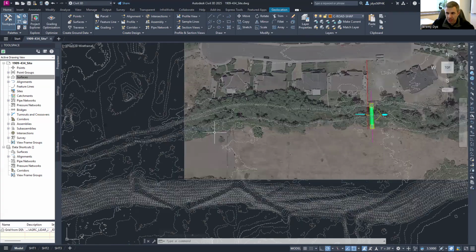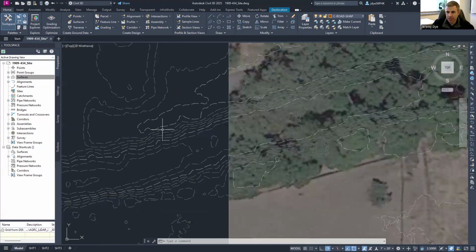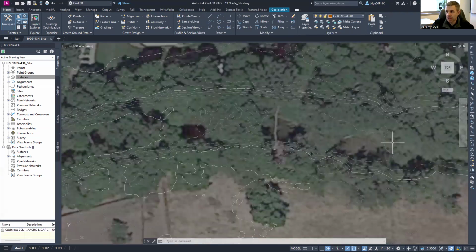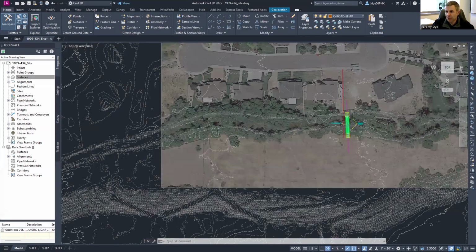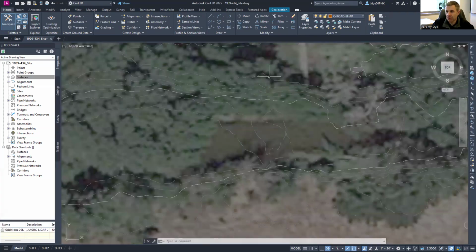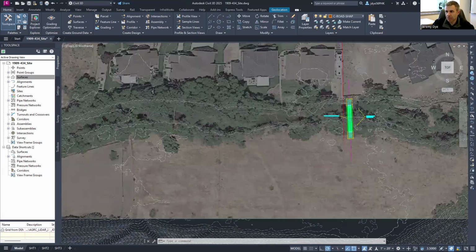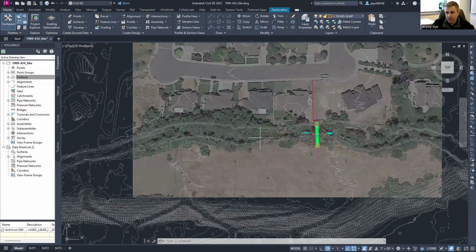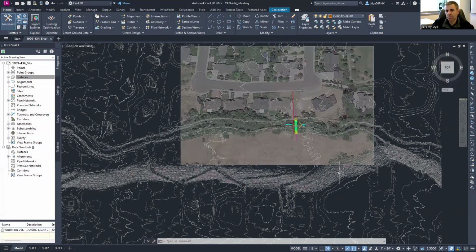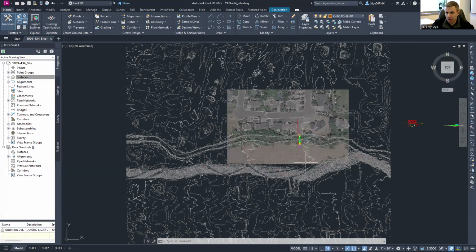You can see from the contour lines, I've got a bunch of contour lines kind of close here. That represents the banks where the sides are steep. Where these contours are farther apart, you can see that's the stream. The stream bottom is pretty flat. So I've got contours, and then up here would be the bank, the floodplain out on the sides. These contours here, that's just a big hill that is off the screen a little bit.